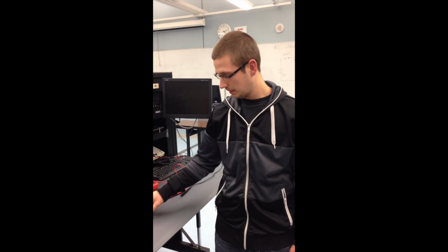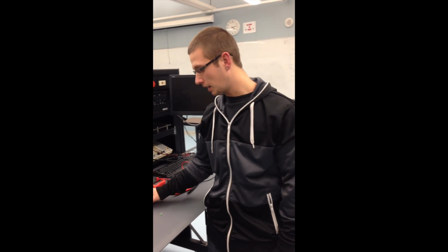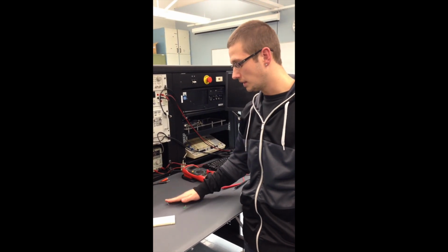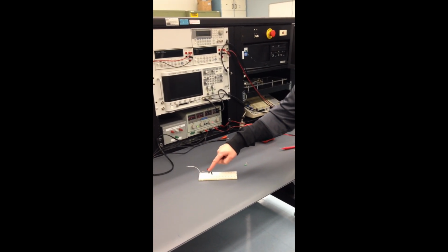Moving on from where Bruce left off, we're going to build the final leg of our circuit. First, you're going to need the green LED. Then you're going to need to get your 1K ohm resistor. And finally, the switch. Keep in mind that you're going to be connecting all these components in parallel with the second portion of your circuit.